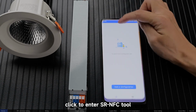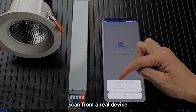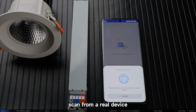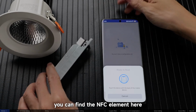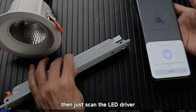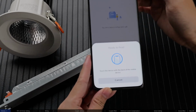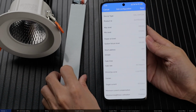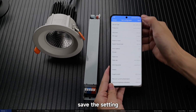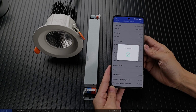Click to enter SR NFC tool. Add a configuration. Scan from a real device. And here, you can find the NFC element here. And then, just scan the LED driver. Okay, scan the LED driver. Successful. Now save the setting. Maybe name it 01 and save.